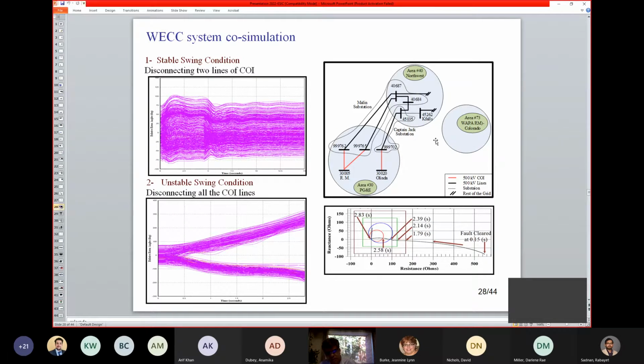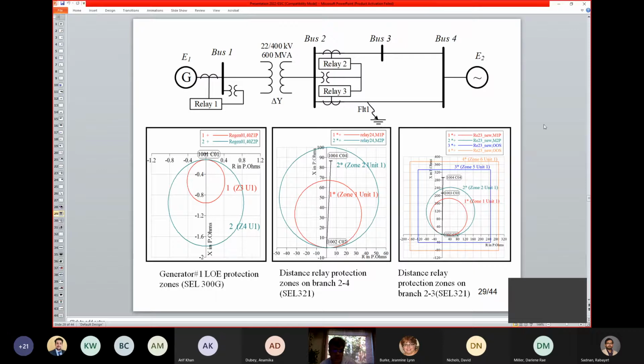At that time, if the swing happened over there, we observed that some protection function in Colorado misoperated, even with the blinders. Then we had this loss of excitation. Again, we implemented different SEL functions. These are not experimental data. They're all in simulation.